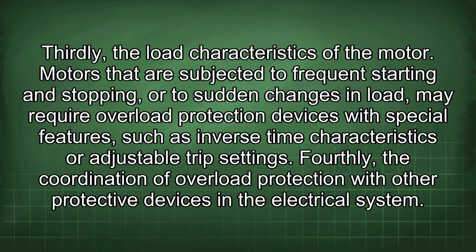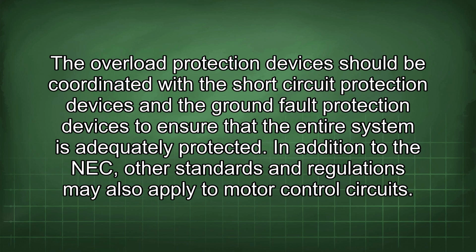Motors that are subjected to frequent starting and stopping or to sudden changes in load may require overload protection devices with special features such as inverse time characteristics or adjustable trip settings. Fourthly, the coordination of overload protection with other protective devices in the electrical system. The overload protection devices should be coordinated with the short-circuit protection devices and the ground fault protection devices to ensure that the entire system is adequately protected.